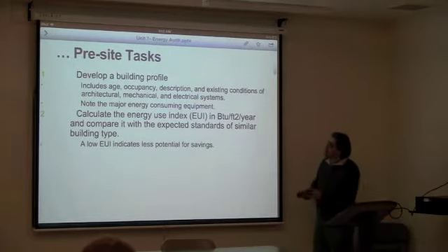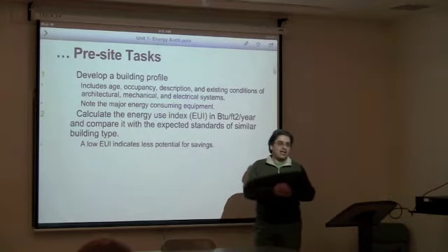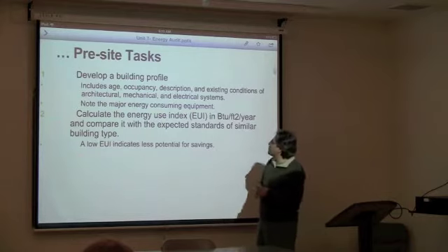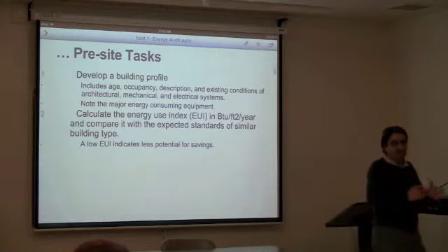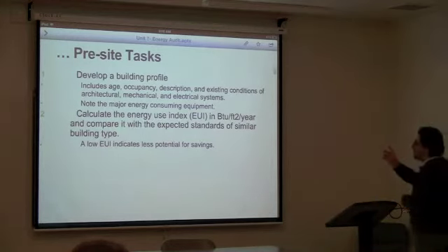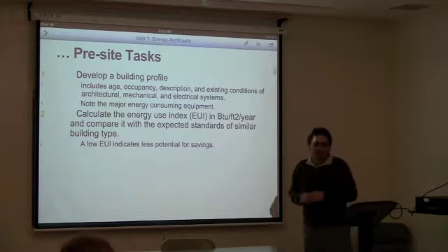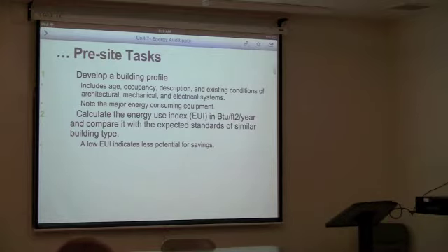Okay. The reason the square footage is very important is that for residential calculation of energy auditing, at the end of the day, what you have to do is calculate all of the energy usages, electricity, gas, all together, divide it by the total square footage of the building, and create a number called Energy Use Index, EUI. There is a standard for EUI for different buildings. If your number is above that standard, something is wrong. Right? So you have to conclude that you need to do an energy investigation, and you need to reduce that number.